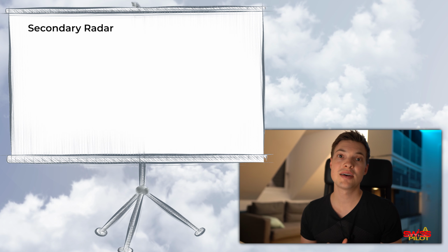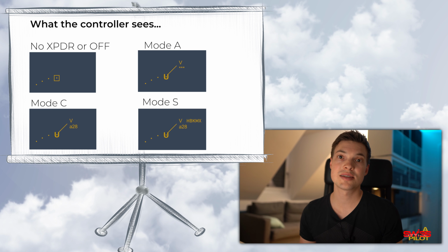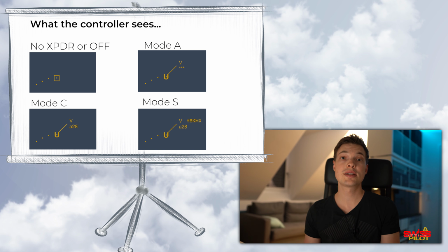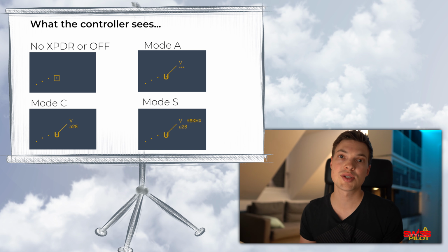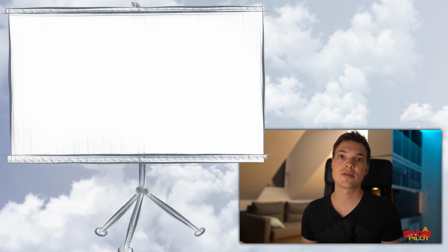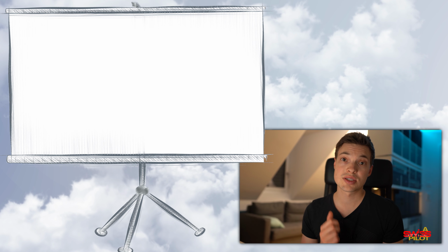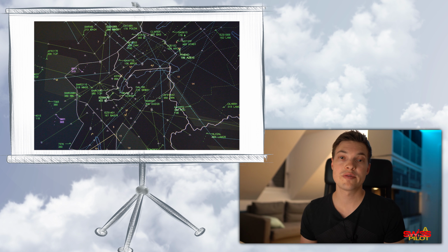In the meantime, the use of mode S transponders has been mandated for a while. These kinds of transponders squitter information, they broadcast information in regular intervals and hereby reduce the number of interrogations that are required to identify and follow an aircraft on the controller's radar scope. They have also solved a couple of issues that had evolved in the even denser airspace environment that we're seeing today.